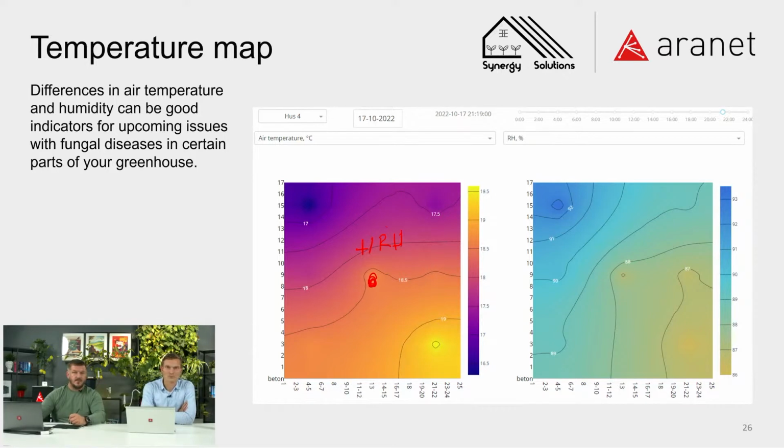And the difference in the temperature and in humidity can lead you to the understanding of why in some corners of the greenhouse, where there is lower temperature and higher relative humidity, you get some fungal diseases on the plant. Like in cucumber, it's Mycosphaerella, and it happens when you turn on your lights and temperature starts to increase. Those plants are at a lower temperature, the plant itself is cold, and it gets to the dew point temperature, and you get possibilities for fungal diseases to grow. So it's a good indication, and it's easy to install.